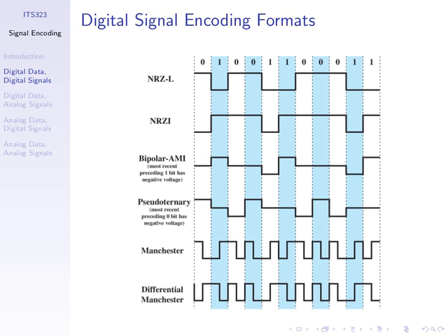That is, if this is 1 millisecond, the clock of the receiver may be slightly off. What is really 1 millisecond is thought of as only 0.9 milliseconds. So sometimes it's useful for the receiver to be able to synchronize to know exactly when the next bit starts. One way to do that is to use the signal encoding to detect when one bit changes into a next bit.